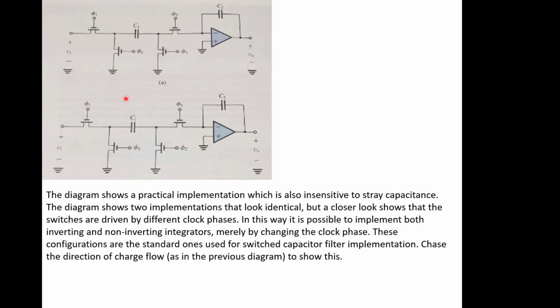You might find that even when you design things properly, you're always going to get possibly little stray capacitances going to ground anywhere, even down through here. Everywhere when you're starting to deal with small scale capacitances, there are going to be little strays that start to become significant compared with the size of the things that you're interested in.